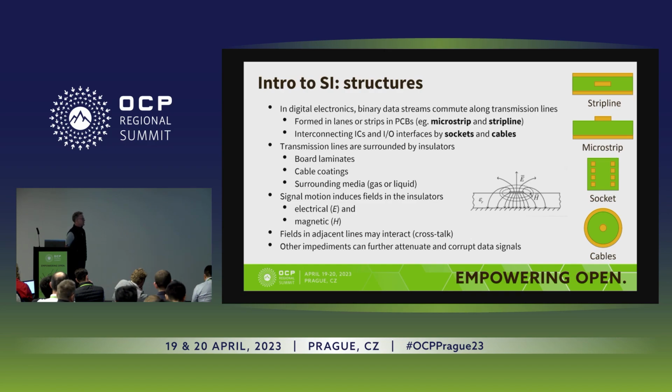Microstrips are different. It's kind of half a strip line, but where we have two dielectric materials around the transmission line. The white space above the microstrip transmission line could be air, or it could be a liquid or fluid, or both in two-phase. So that's where you have an opportunity for things to not go quite right, because when you immerse it, you're going to change one of the dielectric properties.